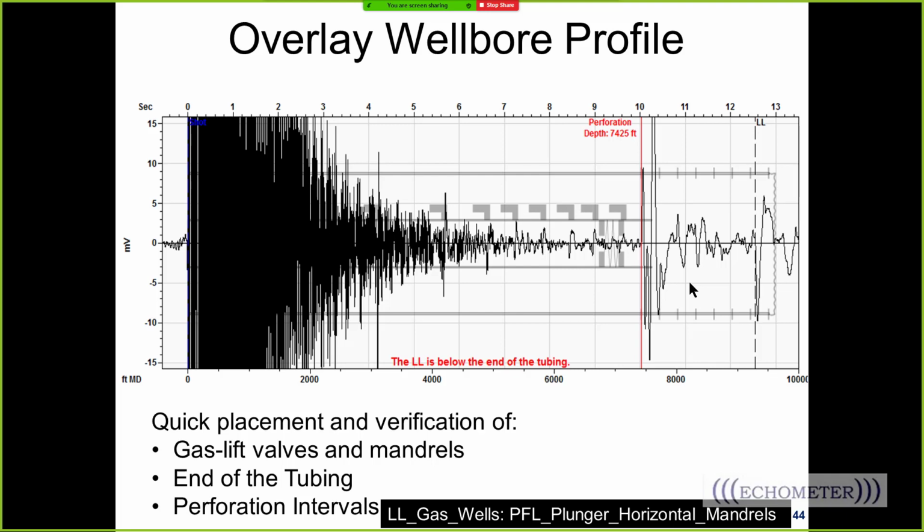So this well is only making maybe 5 or 6 barrels of liquid a day. And so the liquid lays on the bottom, stratified on the bottom of the pipe, and the gas is on top. And you can shoot out the top of the horizontal pipe until you see a dip, and then you see the pipe is blocked, and you see a down kick. So this is a typical example of shooting a level in a gas well, in a horizontal well, where it looks like the tubing just went past the top perf down in where it's horizontal, and you can see way out to a trap, a horizontal trap, where the liquid accumulates, and there's our down kick right there.